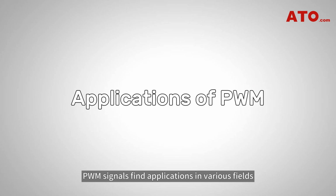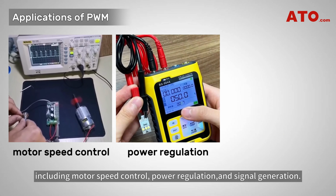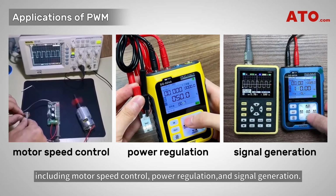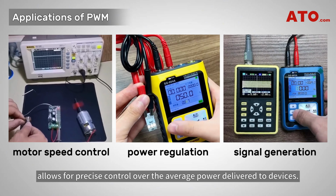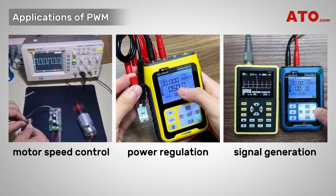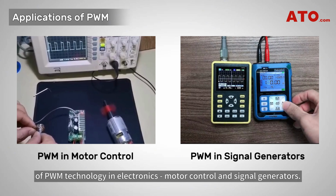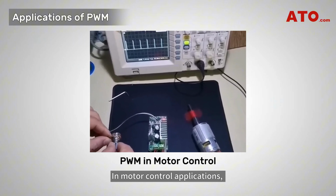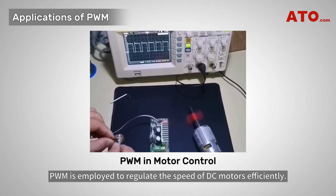PWM signals find applications in various fields, including motor speed control, power regulation, and signal generation. The ability to control the duty cycle of the PWM signal allows for precise control over the average power delivered to devices. Here we want to highlight two most typical applications of PWM technology in electronics: motor control and signal generators. In motor control applications, PWM is employed to regulate the speed of DC motors efficiently.